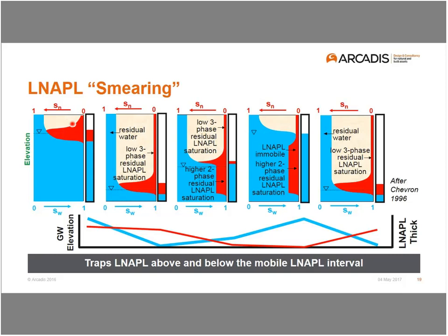So above the water table and above the capillary fringe, we're going to have some air in the pore space, sharing the pore space with the NAPL and the water. So we start out with what's referred to as a shark fin looking distribution of NAPL saturation. And that equilibrates with some thickness of NAPL in a well.